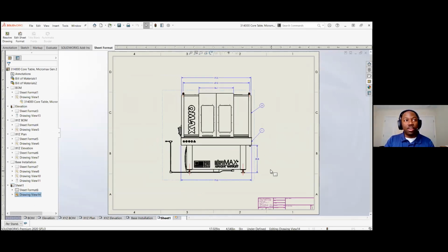And one other thing to note about the model data not even being loaded: this assembly that I have, the actual solid model, I actually don't have that file on my computer. It is just the drawing here. So this can actually also be an advantage if you want to send a drawing to someone without sending the entire assembly to them. So it can be a really quick way to communicate in addition to being able to make those quick edits. So that's all I've got. I'm going to go ahead and hand it over.